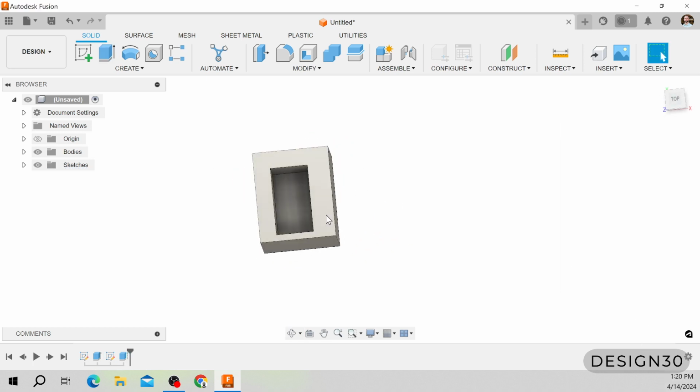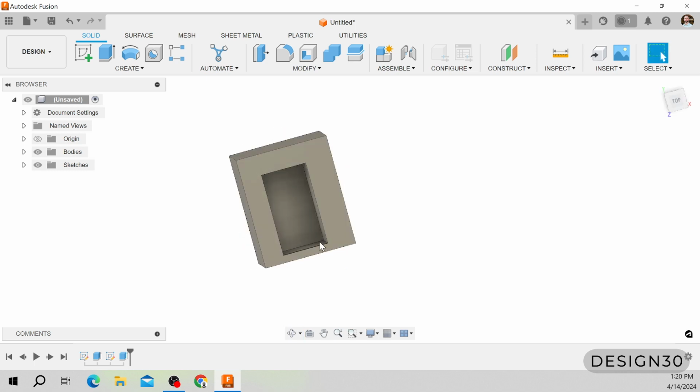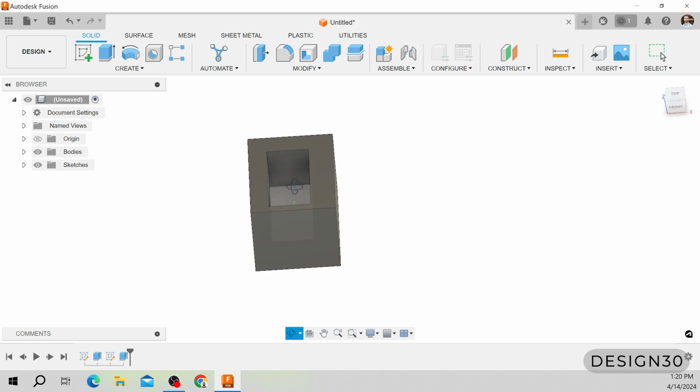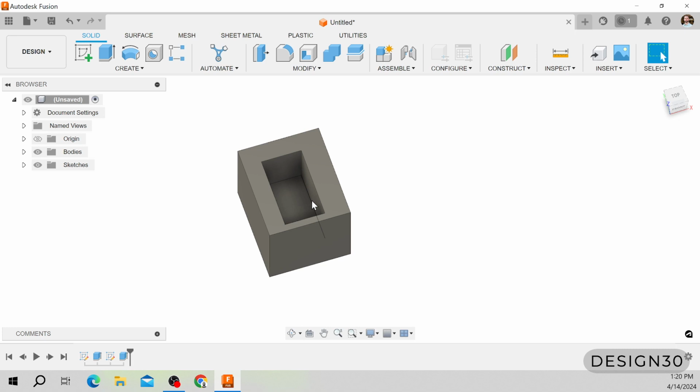And in the future, I'll go through how to use fillets from a manufacturability standpoint. When you're designing parts to be machined, CNC milled, things like that, these fillets actually become incredibly important and are driven by the depth of your pockets, the depth of your cut, what size of tool you want to use, things like that. Whether you're using a square end mill or a ball end mill, there's a lot of different ways you can go about that.